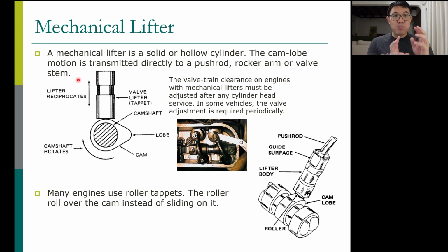Which means that whenever the cam lobe rotates, the valve lift, the valve opening, is smaller and smaller, because the gap or the clearance is larger, right?